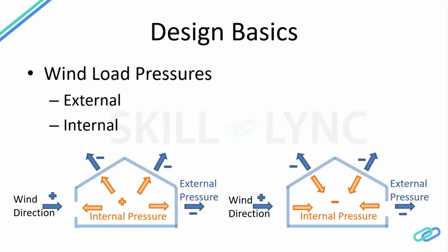Here one important thing is that internal pressure can be plus or minus. You can see on the left and right. When is the internal pressure plus? When it tries to expand the structure. And when is the internal pressure minus? When it tries to pull the structure towards the common center, the center of the building, the center of the room. But the external pressures are just opposite.